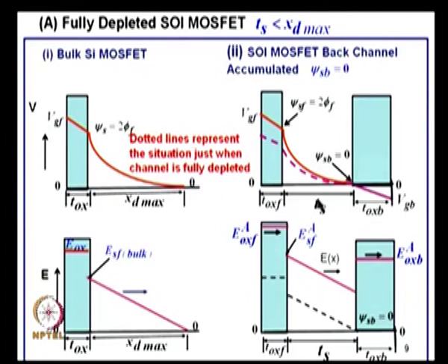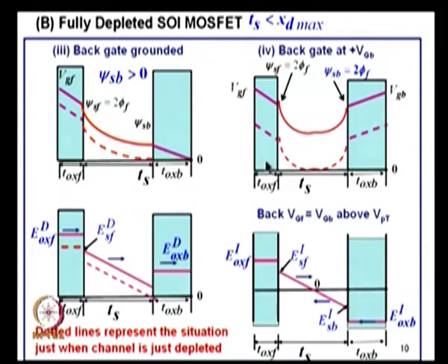We will discuss the voltage calculation in the next presentation, but this is a crucial thing to understand. Before you go to the next lecture, we can go through this once more, and you will appreciate it after going through this again. Okay. So, it is the accumulation condition, but here the field will be higher, surface potential is twice phi f. Now, let us see the other condition. I will finish these two before we wind up for today.